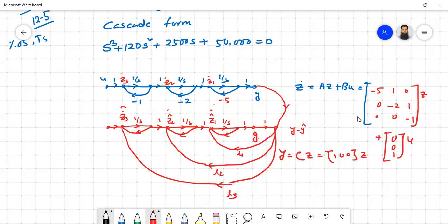You can also say L1Z, L2Z, L3Z, because it is representing the Z domain. Since we have our signal flow graph, and are careful about the signs, we can also feed our original input here. So this is the complete picture of the observer design with just gain.